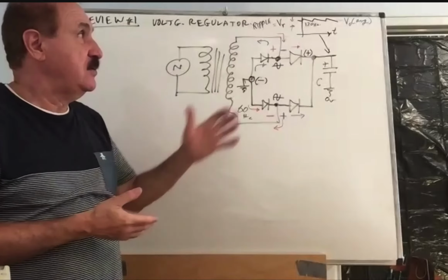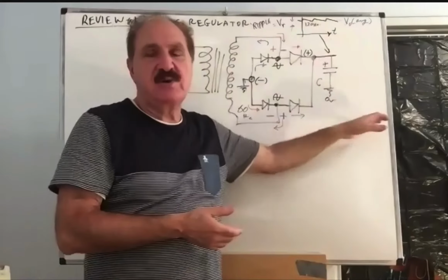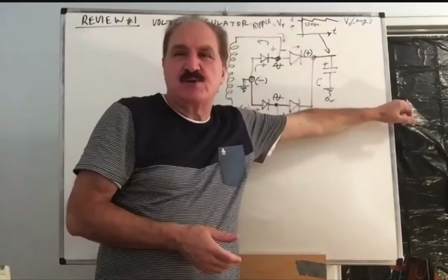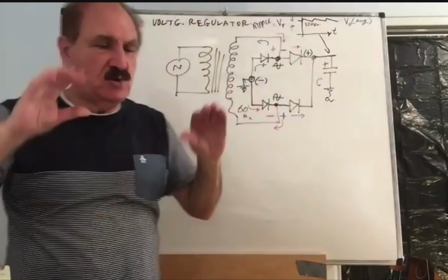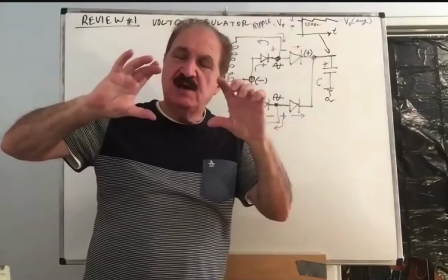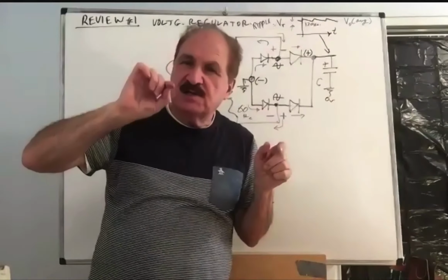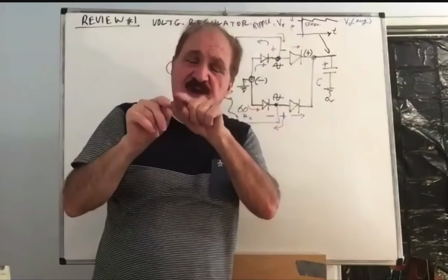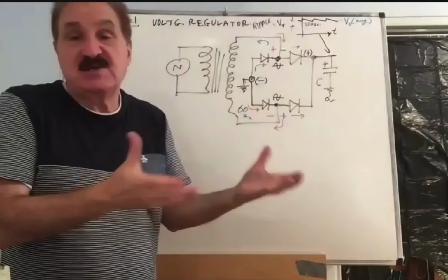What happens if the ripple is large? It is undesirable because somehow it is going to show itself in the final output. By a small amount, but still it will show. So you don't want to generate a source voltage for a circuit that already contains a contaminated sine wave. Well, it's not a sine wave, but a kind of periodic wave. You will hear it in the circuit if it is an amplifier.